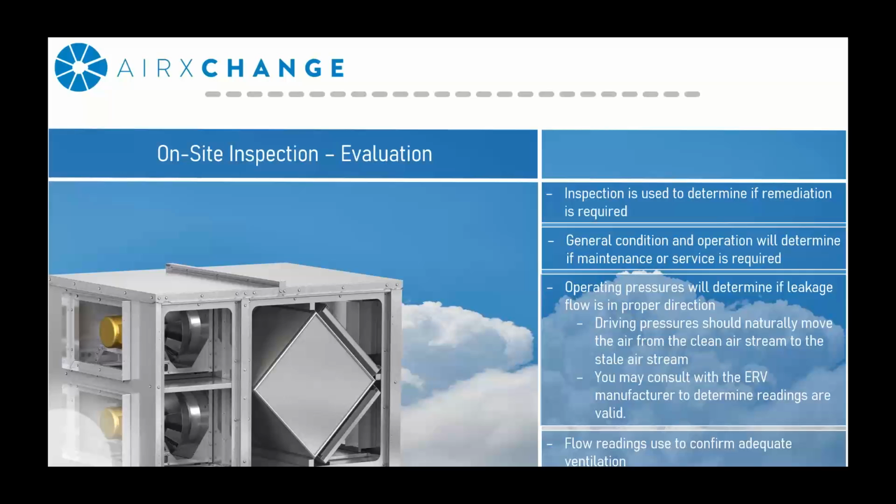Okay, so the inspection part of the process is really used to evaluate any type of remediation that we required to operate the system during the pandemic. So the general condition is going to determine whether or not maintenance or service is going to be required. The static pressures are going to be used to determine whether or not changes need to be made to the fan system in order to achieve the correct recirculation.